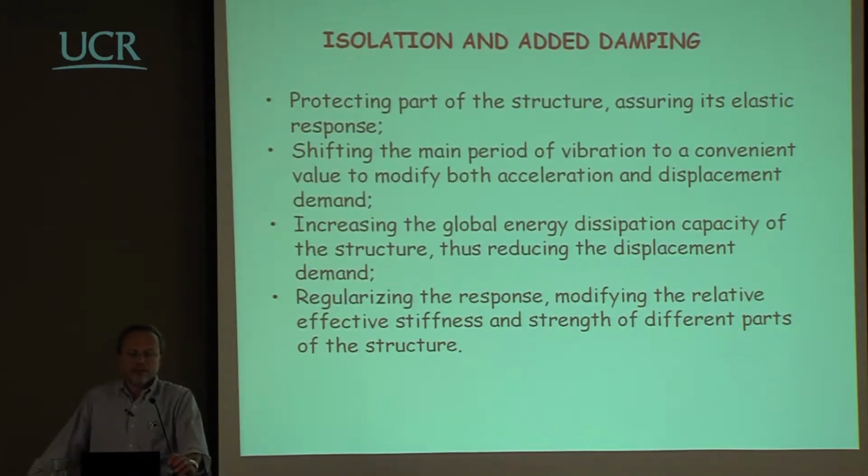So what I would prefer to point out is that we discuss using an isolation system for other reasons. One reason is certainly to protect the structure, in the sense that the isolation system will be used essentially to control the maximum force in certain areas of the structure and therefore to make it easier to apply capacity design principles.